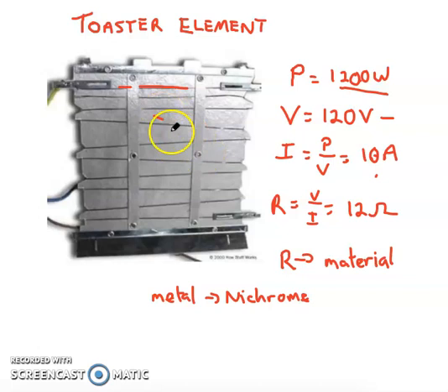Most metals, when you get them really warm in the presence of oxygen, will oxidize, become brittle, and they don't last very long. If you do that to a light bulb filament, in other words, you let air into the bulb itself, it'll oxidize within a second or so and be no good. So nichrome's a cool metal. The other thing that's more subtle, and may sound weird or confusing, is that nichrome is called resistance wire. In other words, it has low resistance compared to most materials, but its resistance, sorry, using the wrong term, its resistivity is higher than the wire that's coming in, the copper wire.